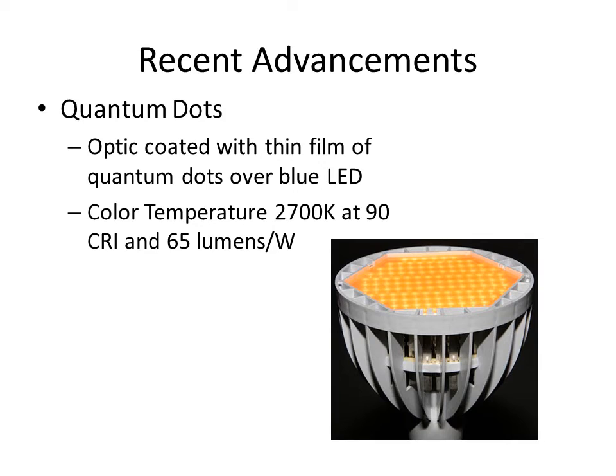Research is being conducted using quantum dots, which are nanometer-sized semiconductor material that fluoresces when excited by photons or electrons. A company, QD Vision, produced an optic coated with a thin film of quantum dots fitted over a blue LED lamp. The lamp produced light that maintains its high efficacy and CRI but at warmer temperatures.